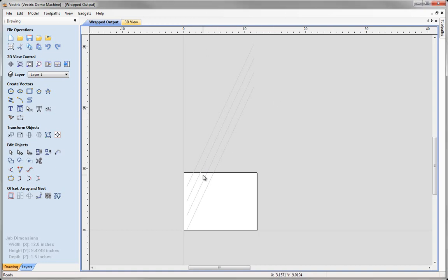This can be a little tricky to understand, but what you've got to remember as it goes around the spiral is that the top edge here is joining up with the bottom edge. So unlike a normal job where this is the top and the bottom and I couldn't go continuously, it's like I can fall off the top edge and already be at the bottom edge here. So as I go up this line, it's going to come up to here, then effectively it'll be like being at the bottom edge going across, then back down and across, and that's how this is going to continuously spiral around my part. It'll probably be a little more obvious what we're talking about when we get to the toolpaths.